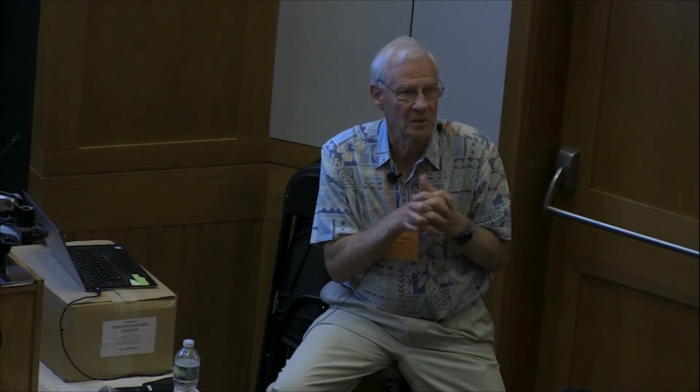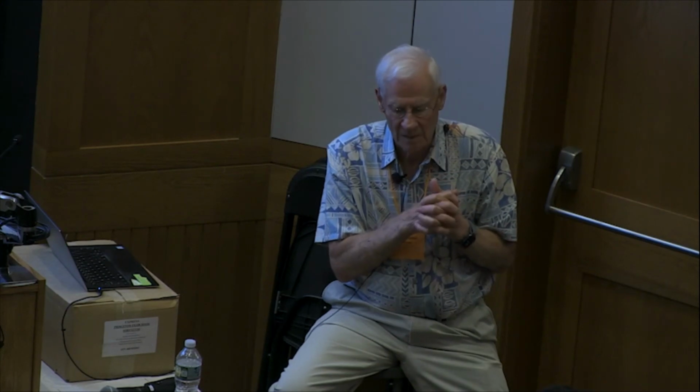So you lose light, we call it extinction, and you can relate that extinction back to the volume of the particles. I wasn't so interested in that. The question was, can we measure temperature of the vapor, even in the presence of particles, whether they're droplets or soot or whatever? Because that's a problem: how do you measure in a flow that has extinction?